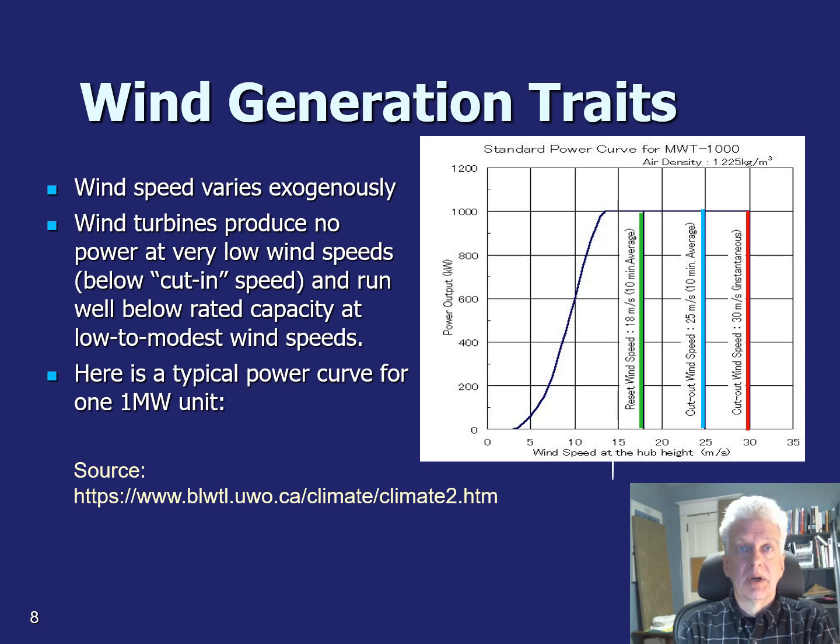Here's the power curve for the output of a specific model of a 1 megawatt wind turbine. And each different turbine design will have its own characteristic curve like this. So you can see that it does an S curve. At very low wind speeds there's no output, because the wind turbine can't overcome inertia and friction. You reach some sort of cut-in speed, and this one is 4 meters per second. It begins to produce a little bit of energy.